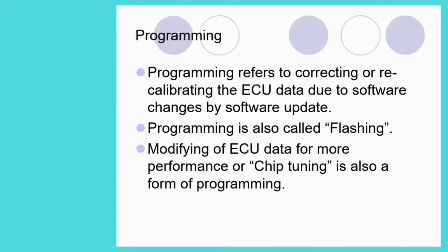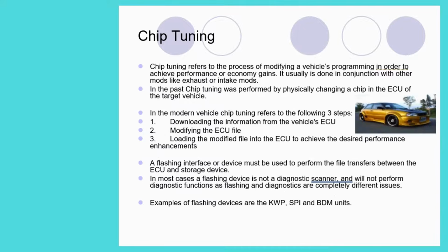Programming refers to the correcting or recalibrating of the ECU data due to software changes by software update. Programming is also called flashing. Modifying of the ECU data for more performance or chip tuning is also a form of programming. Chip tuning refers to the process of modifying a vehicle's programming in order to achieve performance or economy gains. It is usually done in conjunction with other mods, like exhaust or intake mods.